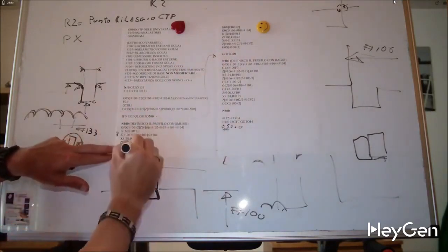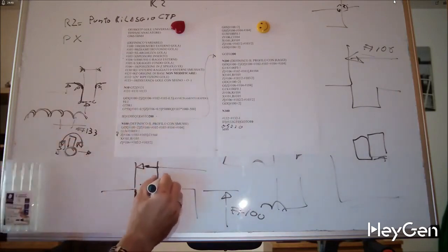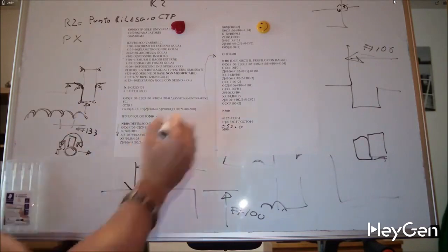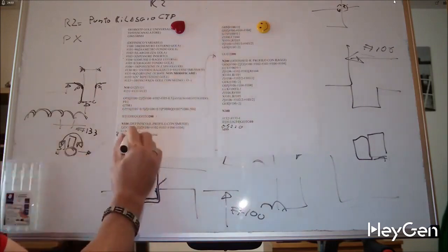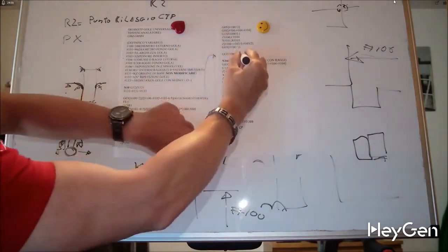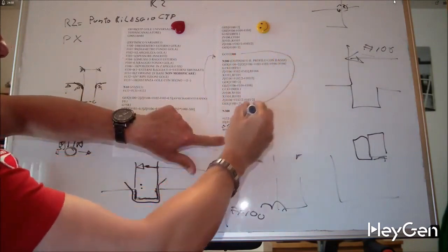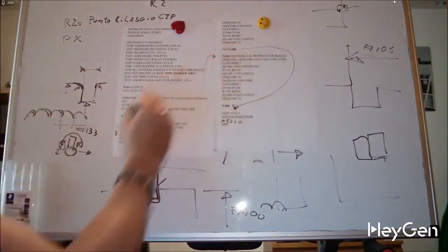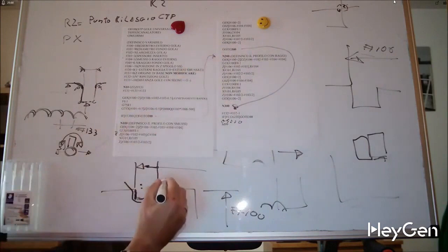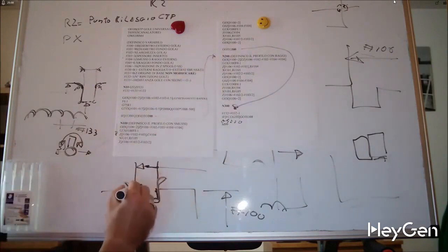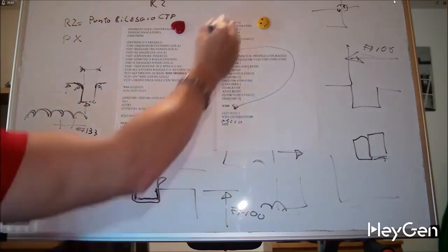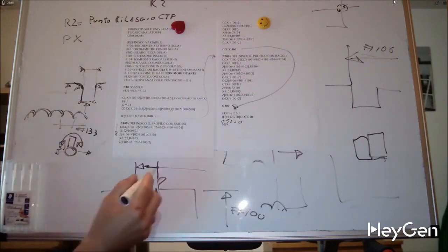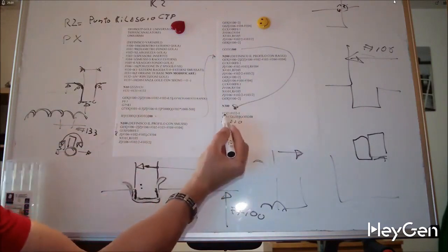This is the program that will finish the insert once I've executed it with the chamfers. I get to go to N300 and skip the execution of N200 because I've already done it. If I accept this jump, I go to N200, and instead of chamfers, I'll do some radii. Okay, so this area and this area are the finishing of the sides and the bottom of the groove. When I get to N300, what do I do?